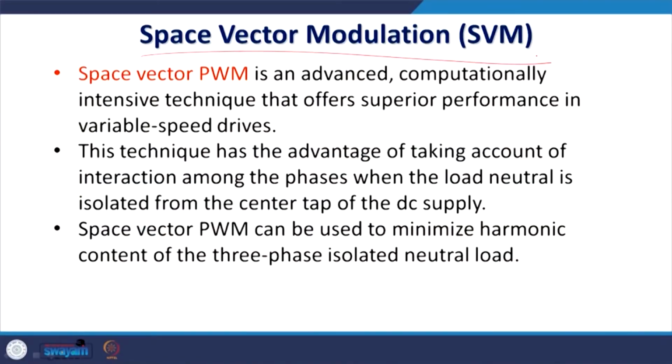This is quite important because most of the drives, as well as the D-STATCOM and the shunt active power filter, now all use space vector modulation because of the greater utilization of the DC bus voltage and because it is more attuned to the SRF, which we have already discussed. The SRF, that is the synchronous reference frame, can directly fit an SRF-based grid connected inverter or converter, such as a solar inverter, shunt active power filter, D-STATCOM or DVR.